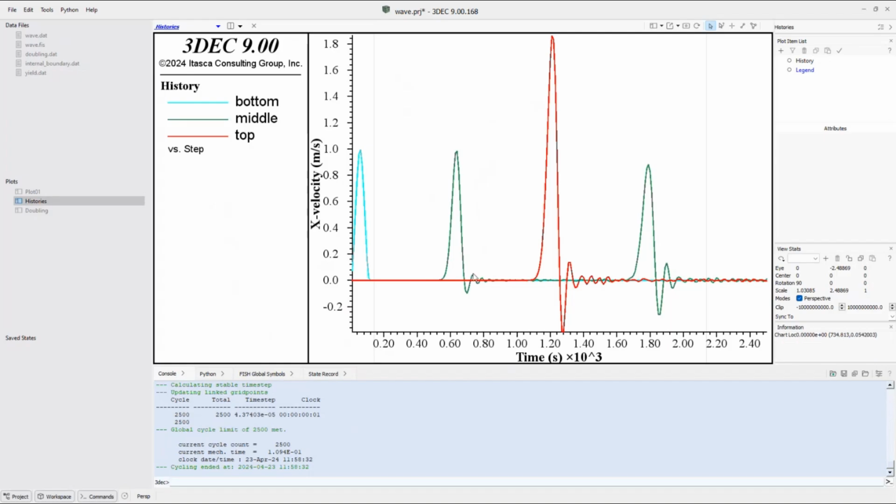You can see a little bit of distortion here. They actually call this dispersion when you get some bleeding of the wave after the time it's supposed to arrive. Bounces off the top, this dispersion is getting worse. It comes back down again, the dispersion is getting worse. So you can see that as you increase the frequencies, you're losing the fidelity of the wave here because you just don't have enough zones per wavelength to resolve it properly. And you can imagine if I make this frequency higher and higher, this gets worse and worse.